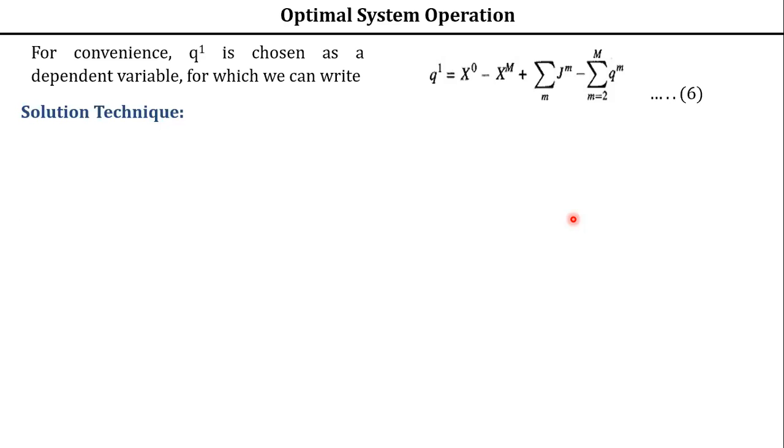So now your optimization problem is that you are saying: minimize the real power generation cost of your thermal plant only, even though it is a hydrothermal power plant we are treating. Still we are minimizing the real power generation cost of the thermal plant only, because you know that the operating cost of the hydro power plant is almost negligible or zero, isn't it? And with that we had 3 constraints. So that is your optimization model or optimization problem.